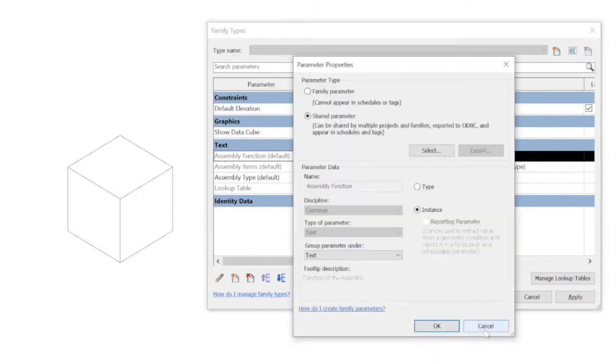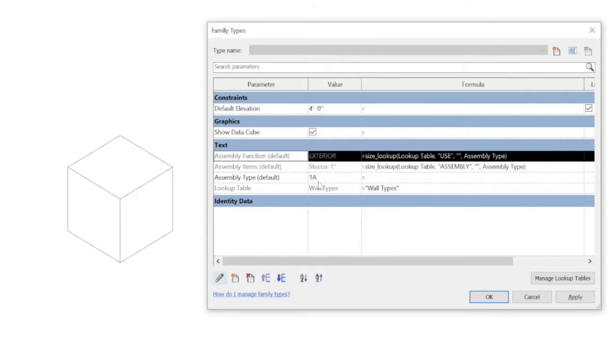So now we're able to have these shared parameters applied, and this can be any name you want. Shared parameters you already have in your business, that's fine. In this case, this video is to show the principles of this methodology that you can customize however you need to fit your existing standards in your business. What we're doing now is looking at this lookup table we're about to create. When a host has a certain assembly name for a floor, wall, or roof assembly, it's going to look at that lookup table for this value, and it's going to push back out the results here, which would be in this case our multi-layers of our wall assembly.